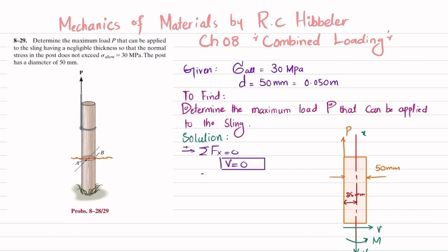Now we will find this vertical force by using this equation of equilibrium, that sum of all forces along Y direction must be equal to 0 and upward force is taken as positive. So P and N are acting vertically, so P is upward, so P positive and N is downward, that is equal to 0. So from here we will get N is equal to P.